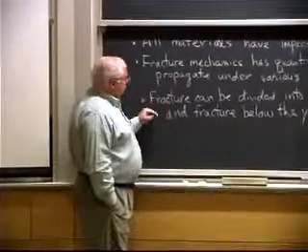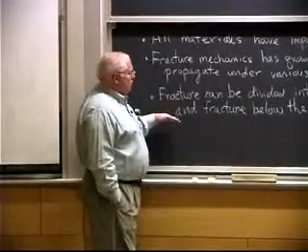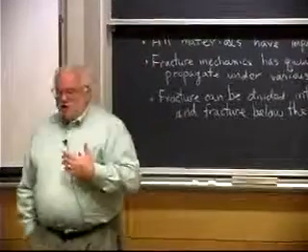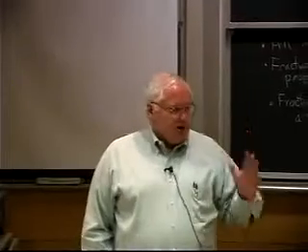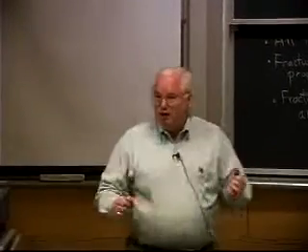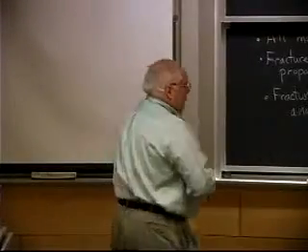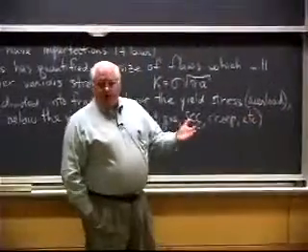Generally, on a very crude scale, fracture can be divided into fracture above the yield stress, which we call overload, and fracture below the yield stress, which are all kinds of types of fracture. There hasn't been a lot of study on overload fracture because we can calculate that. People could calculate that in the 1880s, just force per unit area. Is it above a certain value of yield stress or not? And if we were talking about a ductile metal, you can see the parts stretch and deform before the thing breaks. It was overloaded.